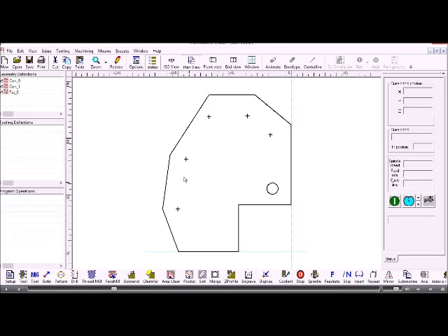The screen layout, across the top of the screen we have the options for setting the view and setting the tool and running the job. Now some of these commands are greyed out because we haven't got any commands to simulate, therefore we can't press the simulate button. On the right hand side we see a status panel, and that will show us where the tool is, the current spindle speed, the feed rate and the cycle time. The main graphics area in the center is where we'll see the tool moving on the screen.